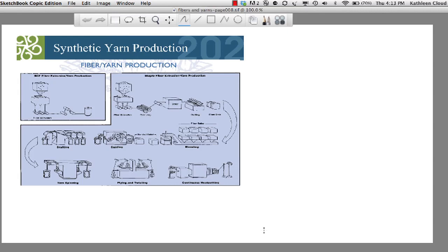After fiber extrusion, post-treatments for staple fiber, including drying and annealing, which is a heating and cooling process, increase tensile strength and generally enhance the staple fiber's physical properties. The filament bundle then goes through a crimping or texturing process that converts straight filaments to ones with a repeating kinked, curled, or sawtooth configuration. The blending process, so we do have the blending process to start here, then mixes the staple fibers from different bales to ensure that the fibers intermingle in a way that yarn streaking will not occur in subsequent dyeing operations.